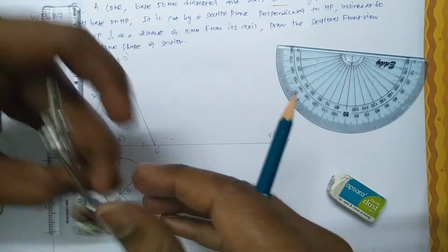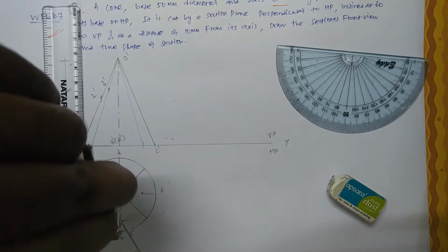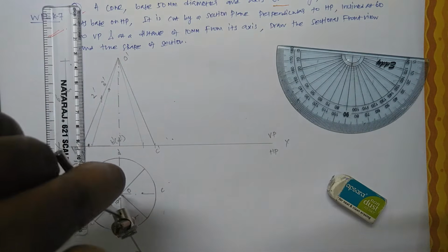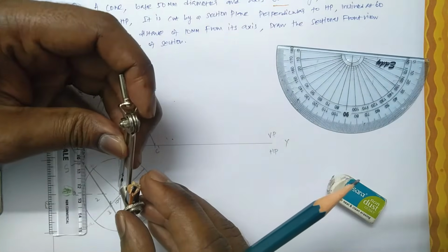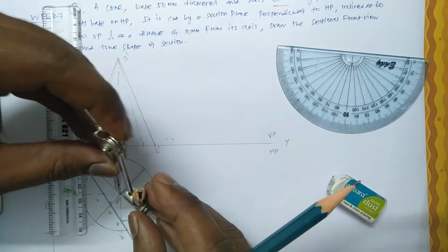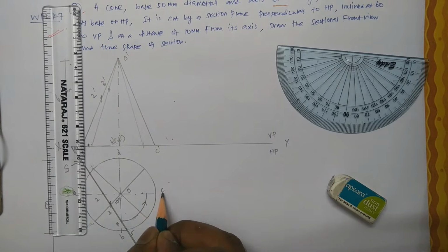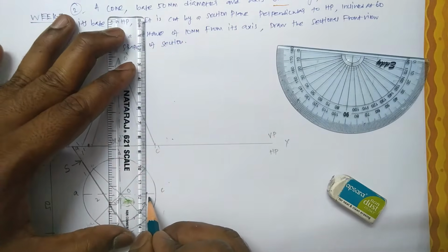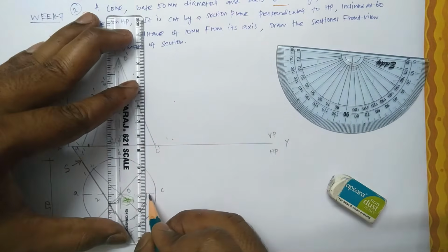See, you just keep O as a center, 4 as a radius. You just draw one curve, just draw one curve which touches C to O dash, immediately erect a vertical line. This is the point, you can say this is P usually.